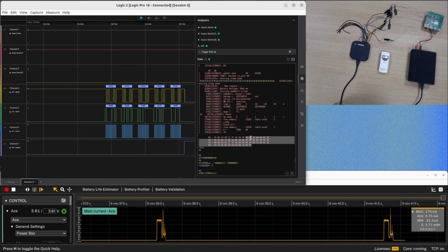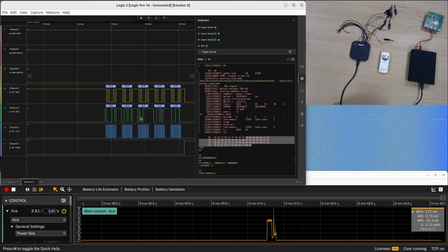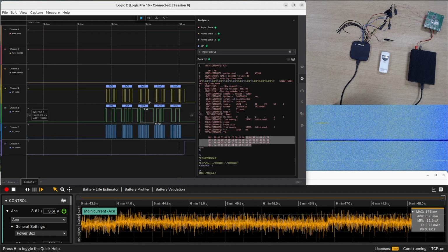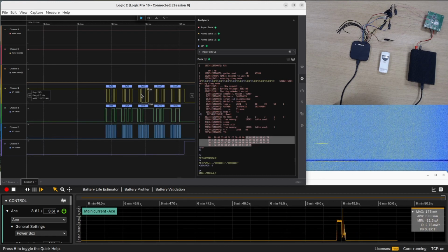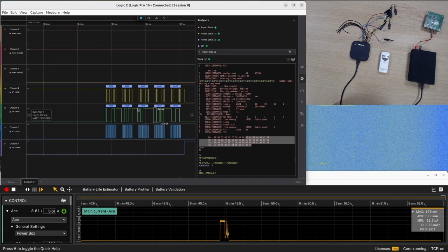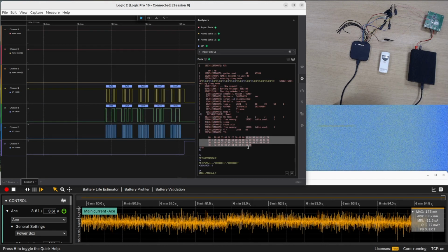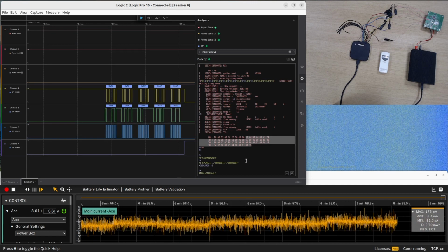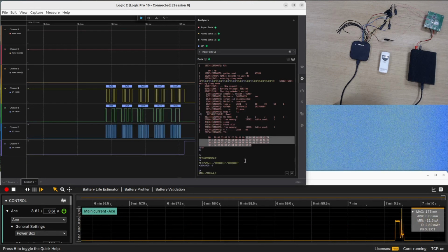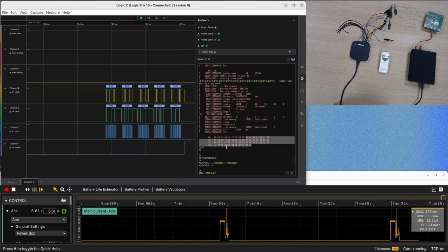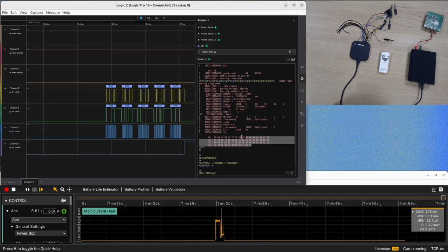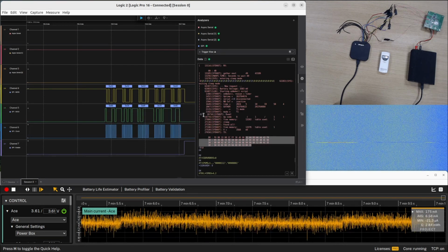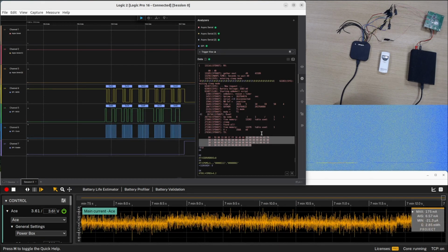What we could do is look in this analysis for the command where the FIFO of the receiver is being read out, and then we could read this data out of the FIFO. We would not read it in a raw format like this, because it's wireless M-bus T1 mode, so there is some encoding which we would have to apply, and there is too little time here to really go through this. But this would be the approach we would use.